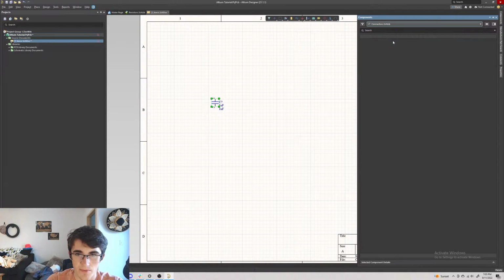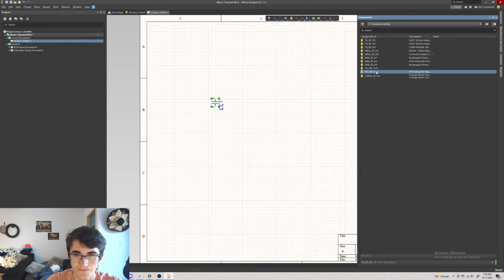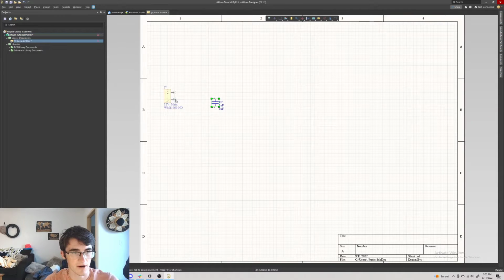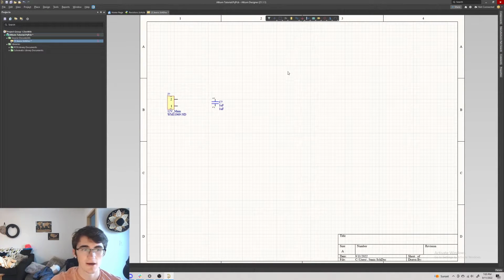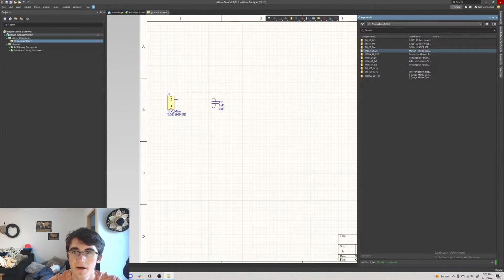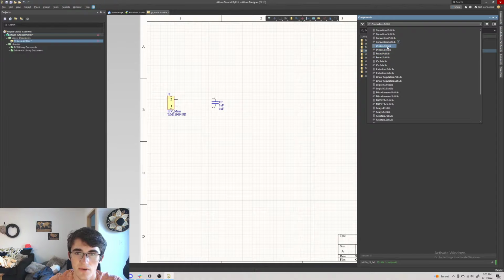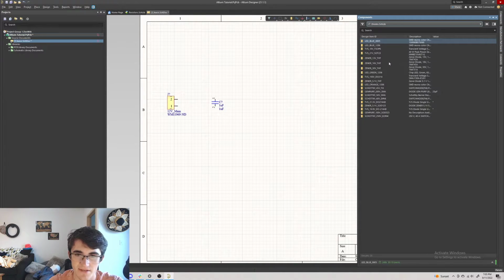We can get a couple other parts. We can get connectors. So we have a 4-pin, we'll do a 2-pin Mega-Fit connector. On Solar Car, these are very common to be used for 12 volts and ground going into the board and out. That's something we changed last year. So that'd be cool. Let's get a diode on there, maybe just filter something.